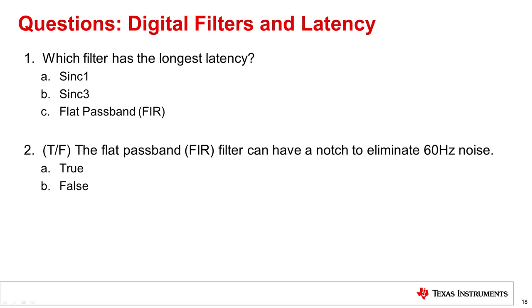Question 1. Which filter has the longest latency? A, Sync1, B, Sync3, or C, a flat passband, also known as an FIR filter? The answer is C. The flat passband filter has the longest latency.